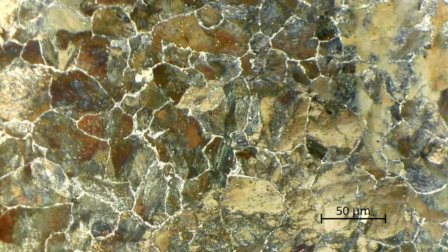This micrograph shows the microstructure of a hypereutectoid steel with 1.2% carbon under the microscope. The relatively broad grain boundaries of cementite can be seen. They appear whitish due to the special preparation of the sample to make the grain boundary cementite visible. The individual pearlite grains are very difficult to resolve under the light microscope and appear as brownish grains.